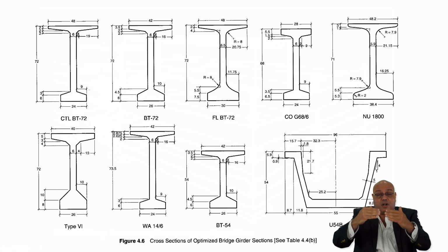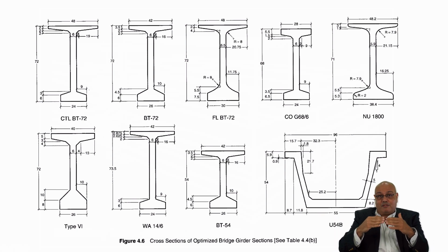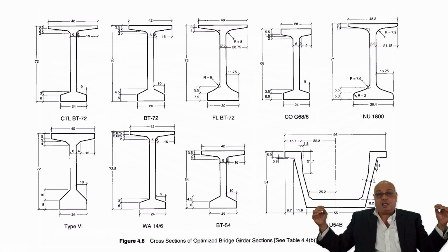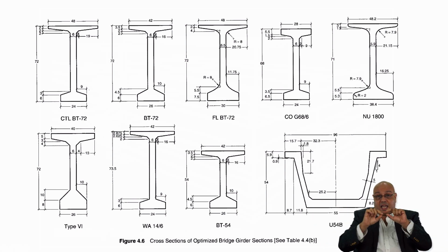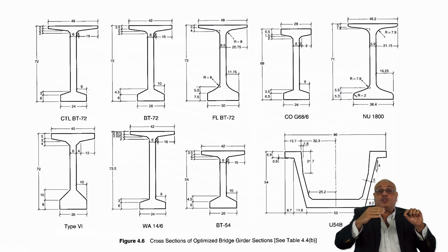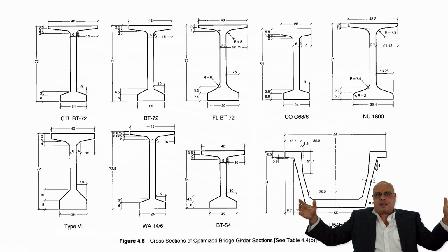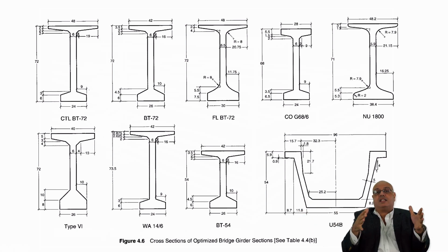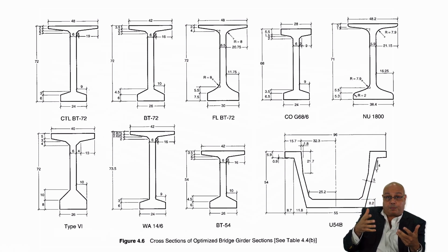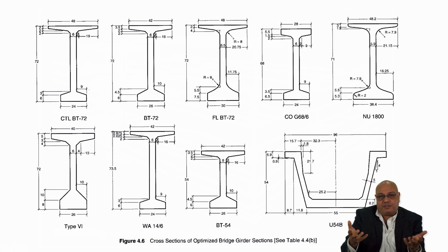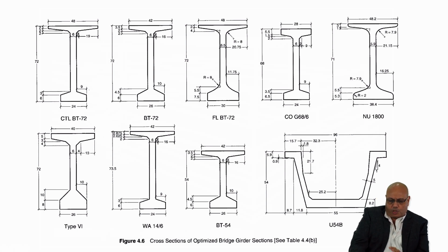Now we go to another level, which is a totally new level, wonderful, which is to apply a prestressing force by having cables that are 4 to 5 times stronger than the reinforcing steel, apply a tension force to them, and then release this force. So the concrete itself is going to be under compression. And the beauty of having the concrete under compression is that the concrete itself is able to carry this kind of compression. So we're going to go through this and see how much gain we got.